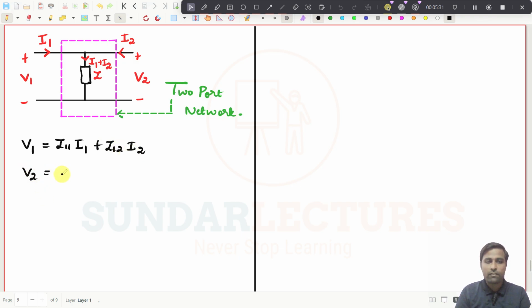For V2, it will be Z21 I1 plus Z22 I2, right? It is a very simple circuit, so you don't need to open circuit or short circuit and do so many things to get the values. It is very simple.